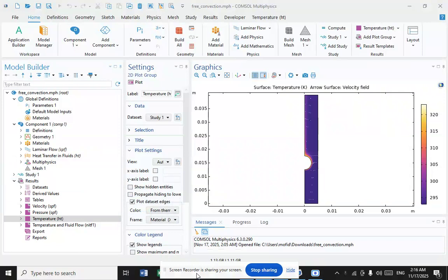Heat transfer by free convection, also called natural convection, is a process where a fluid moves and transfers heat due to density differences caused by temperature variations without an external force like a fan or pump. Warmer, less dense fluid rises while cooler, denser fluid sinks, creating a natural circulation loop that carries heat. This process is responsible for phenomena like atmospheric and oceanic currents, a hot drink cooling, and the circulation of air in a room.